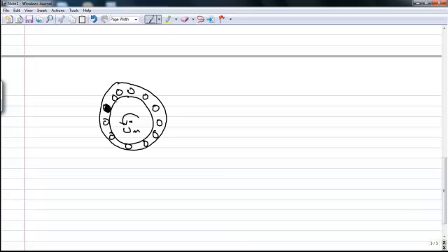So the polarity of the induced voltage is into the page. And the lower bars, here we consider that B sub s is in this direction. The velocity of the lower bars is out of the page because it is moving in the opposite direction. It's moving to the left relative to B sub s. So the result is that we get a current out of the upper bars and into the lower bars.